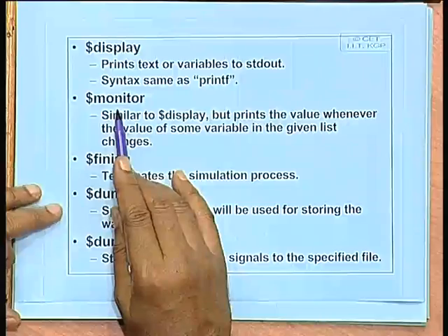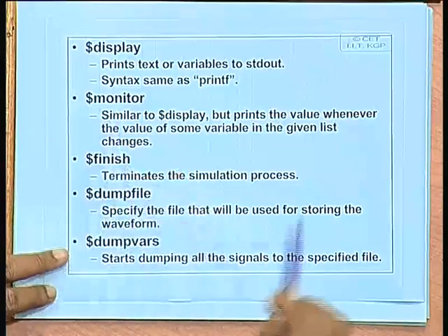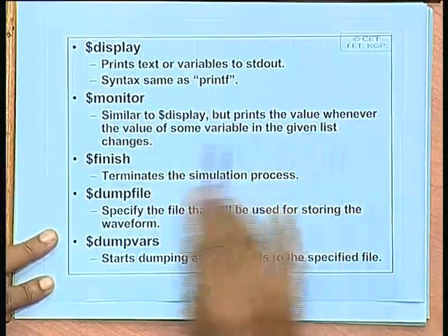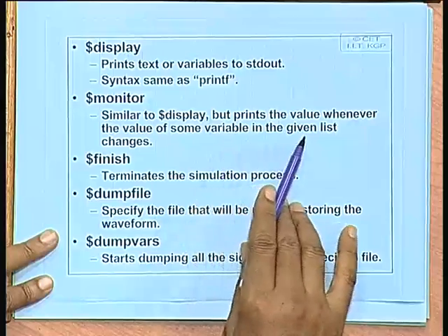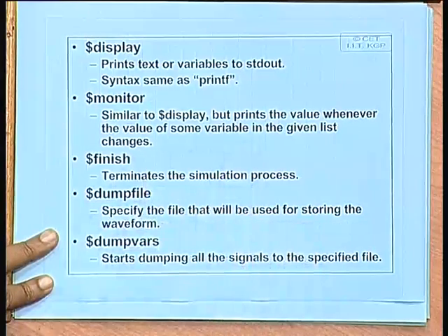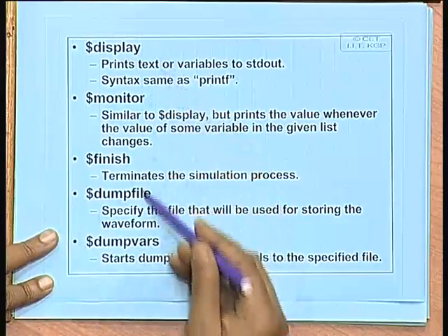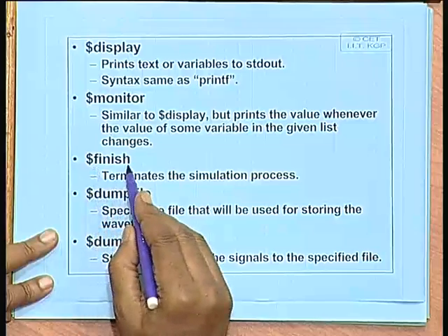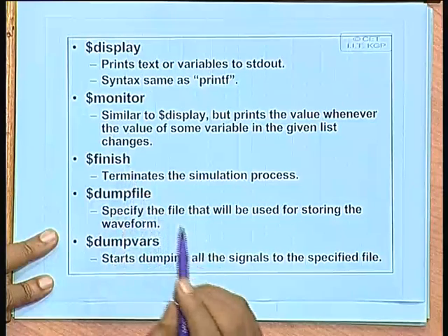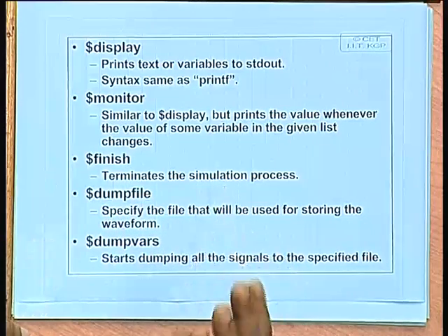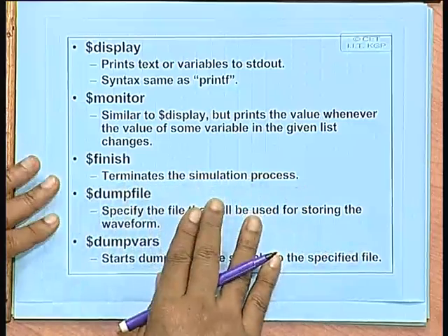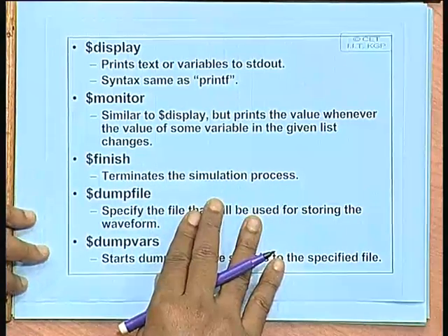So, that will give you the result of the simulation. You can exactly see at what times the values are changing. Okay. So using the monitor command you can do this. It prints the value whenever the value of some variables in the specified list changes. At the end of the simulation, you give a finish command which tells the simulation to terminate and close all the files which it had been using. Okay.